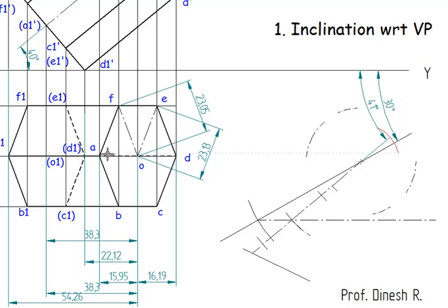Now from the A point I'll take this distance. The A to E distance will be equal to the A to C distance. From this point I'll cut an arc of 32.4. Then I'm going to take the distance from A to F, just 23.09.